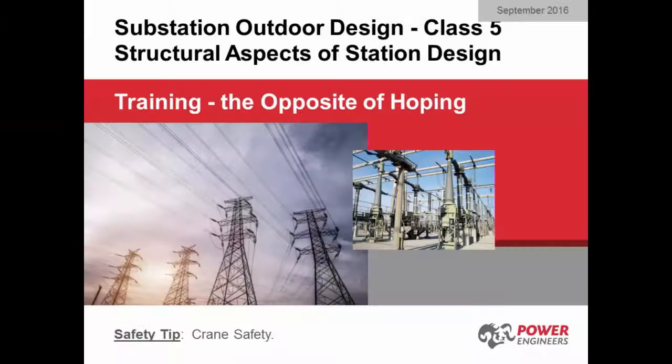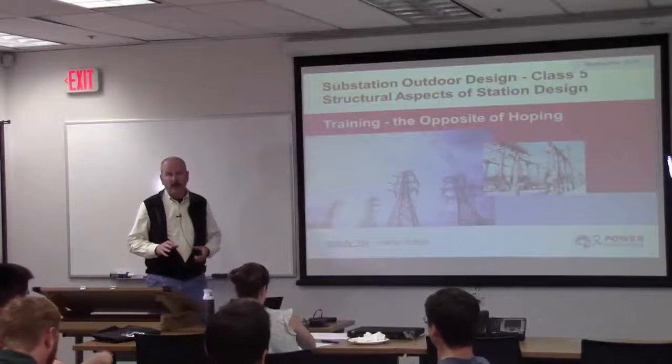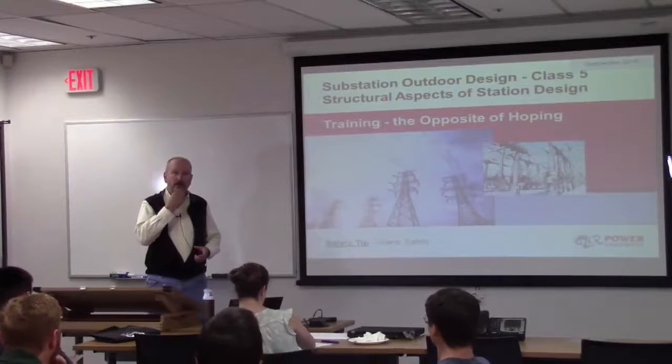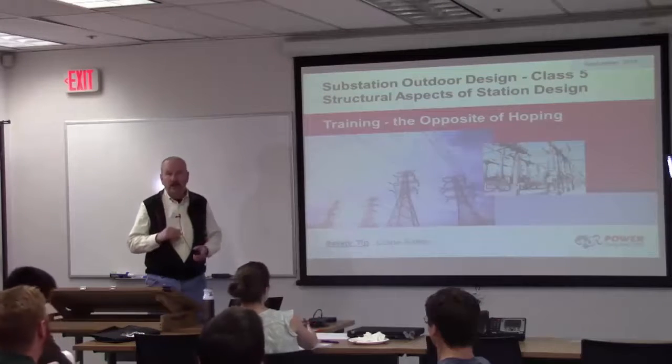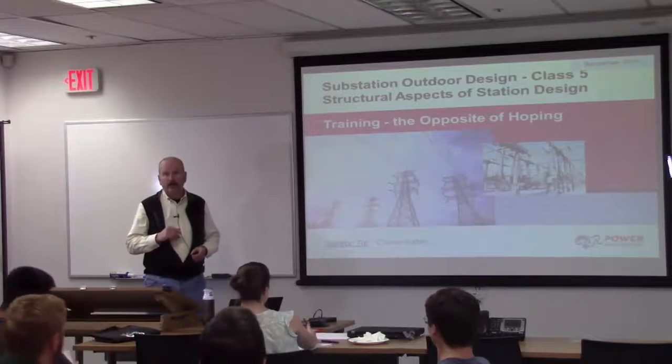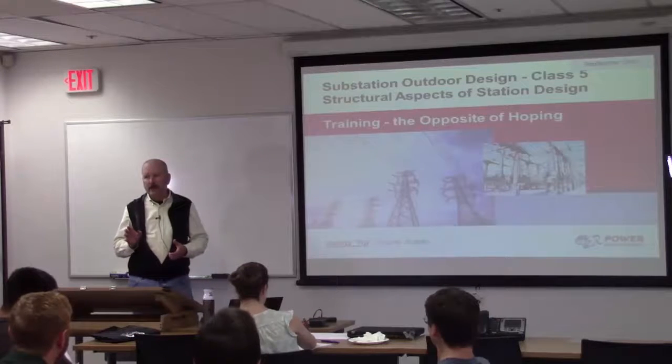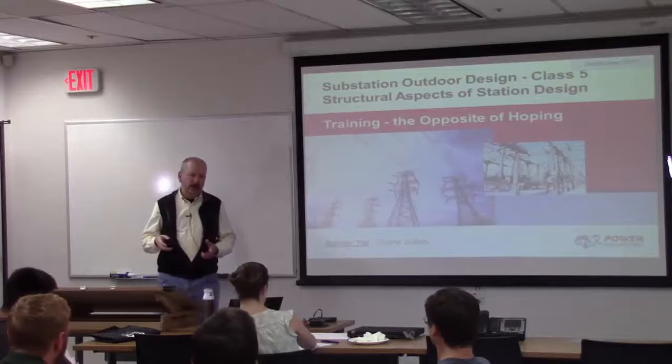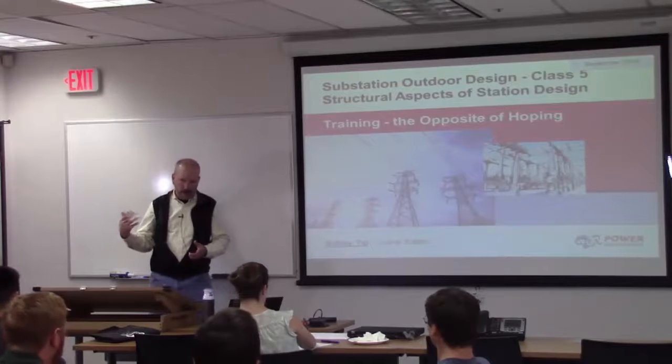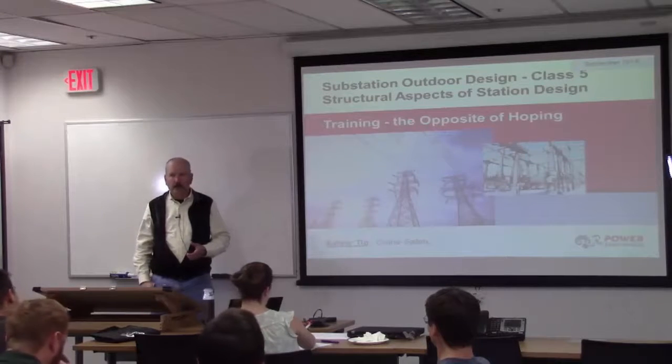I want to start off with a safety tip and talk about crane safety. If you're out at a substation and it's under construction, there happens to be a crane in the station at the time that you're there, you're now getting to see probably the most dangerous piece of large equipment that we deal with. And so if there's a crane active in the station, you always want to be aware of it. There should be a safety briefing, or whoever's in charge of safety at the site should be coordinating with you.